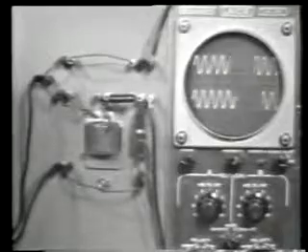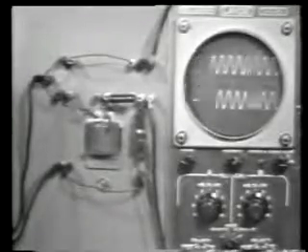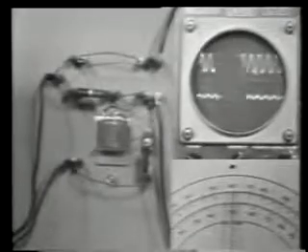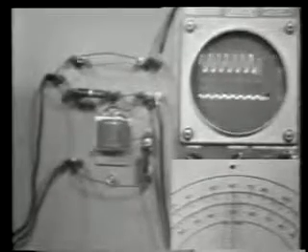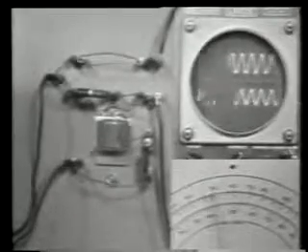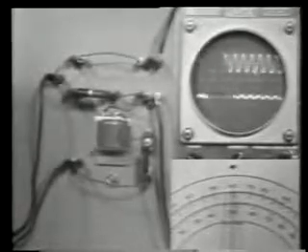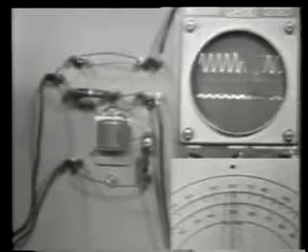Now earlier we found that we could make a low-pass filter perform as a high-pass filter simply by reversing the position of the series and shunt components. Well, the same thing is true of this band-pass filter. By reversing the components, as we've done, we can cause the circuit to now reject a band of frequencies and pass all others. In other words, it becomes a band reject filter. Let's see how.